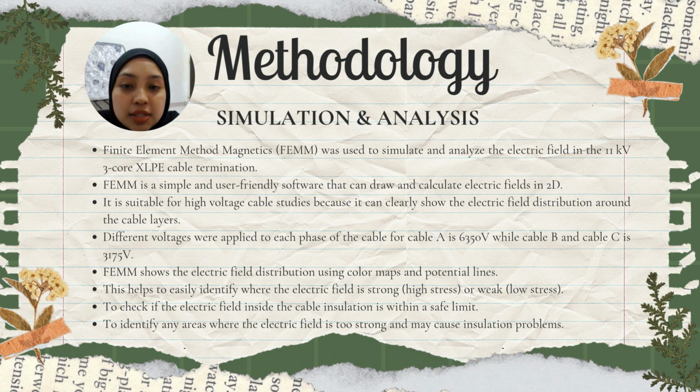Next is simulation and analysis. In this project, finite element method magnetics (FEMM) software was used to simulate and study the electric field in the 11 kV 3-core XLPE cable termination. FEMM is an easy-to-use program that can draw and analyze electric fields in 2D. It is very useful for high-voltage cable study because it can show how the electric field spreads around the cable layers in a clear and detailed way.